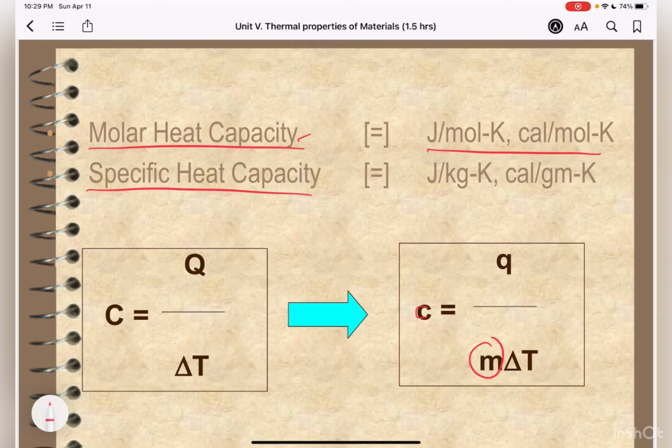So there are two ways in which this property may be measured according to the environmental conditions accompanying the transfer of heat. One is the heat capacity while maintaining the external pressure, what we call your Cp. And the other is, of course, the heat capacity at constant specimen volume, or that is Cv. I think you're familiar with this already from chem or thermodynamics.